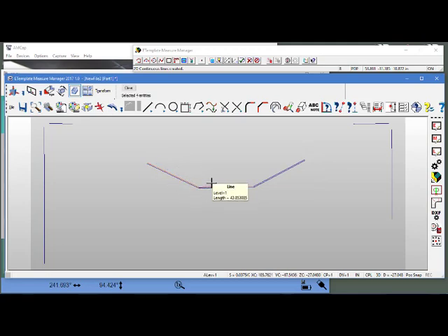Well, I still remember what it is I want to delete. To delete multiple lines, I'm just going to use this little Japanese sword thing, and it'll take all of those out. Okay, now I've got to do some trimming. And I'm going to use the Smart Trim tool. Smart Trim both. It tries to anticipate what I'm trying to get to. And then on this, I'm going to use extend this line to this line. Extend this line to this line. Just doing a manual trim so you can see the difference.